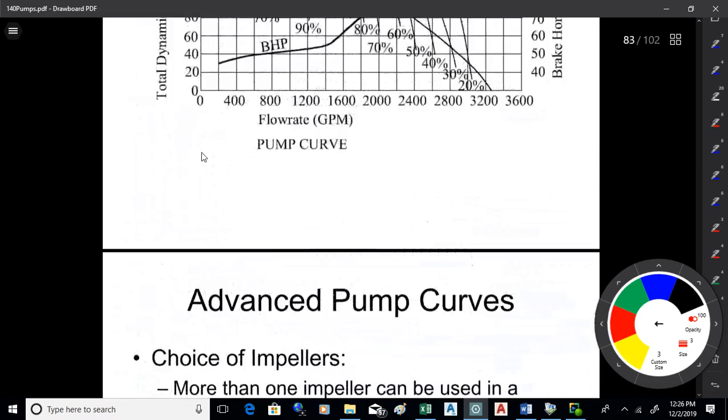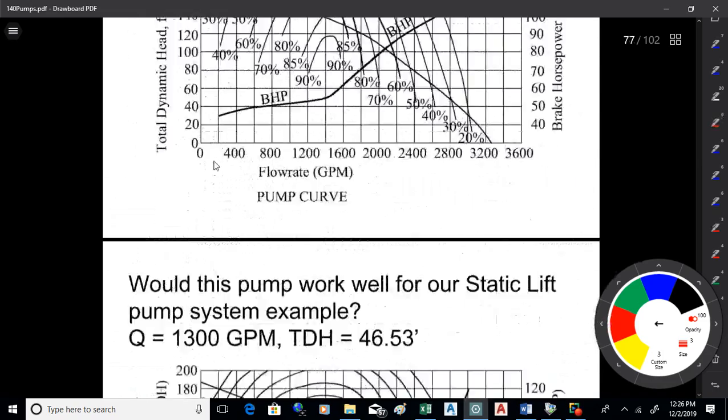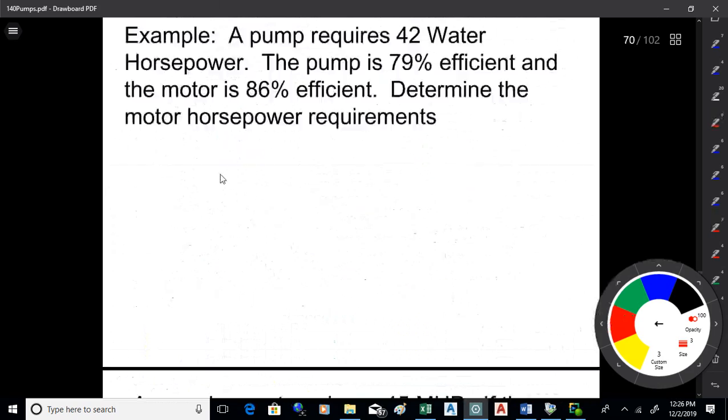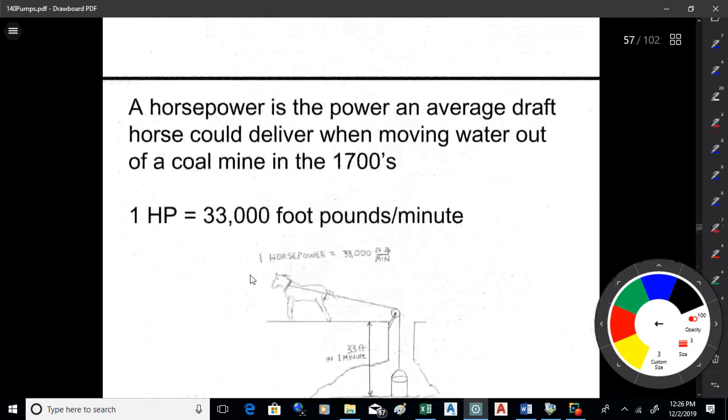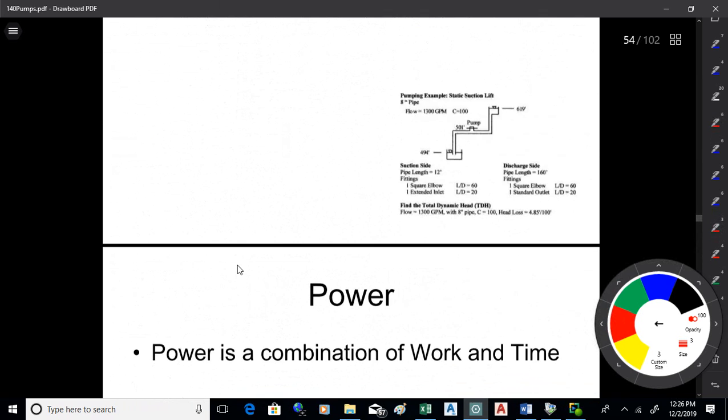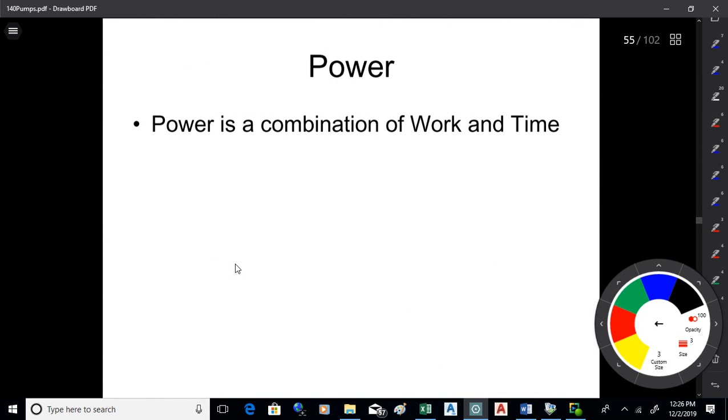Okay. And what we're doing here is just running some numbers to kind of show what's going on there. Cavitation's caused by not having enough energy in that water that hits the pump, and that can lead to the water vaporizing, and then those vapor bubbles hit that high pressure area in the volute, and they just collapse in. They kind of implode. They don't explode, they implode. And that can just chew up your pump pretty bad if that happens. So we good with that? Okay.